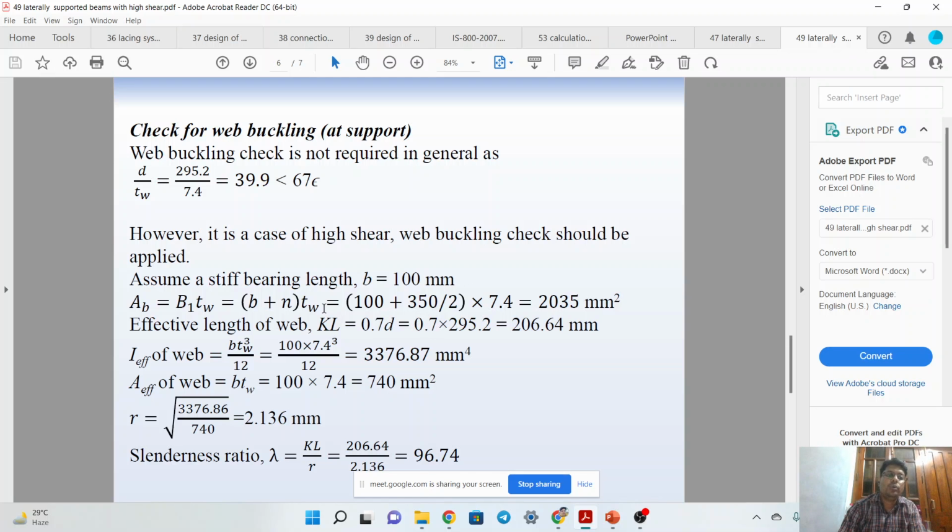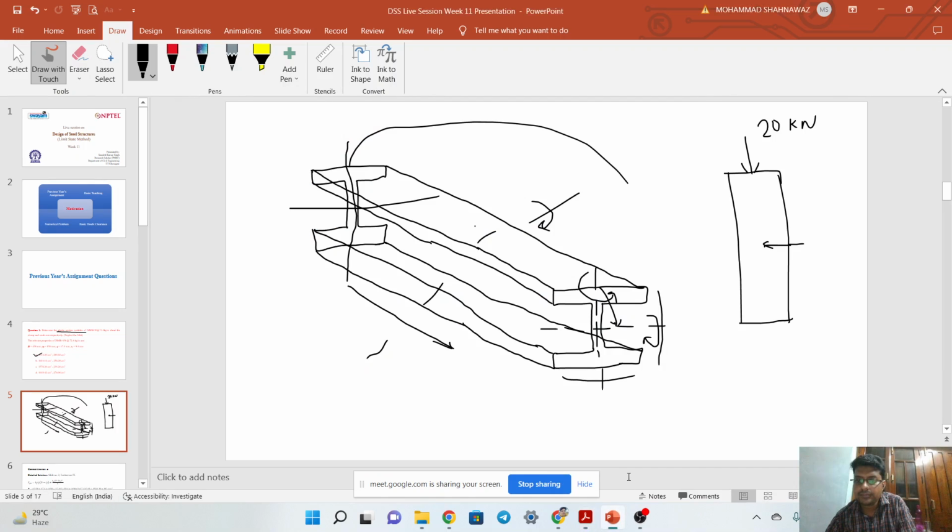So these are lateral dimensions. Remember one thing: whenever you get confused, you can always assume in layman's terms like this. Let us suppose you are provided with a rectangular column, and you see that after applying some load, it is buckling. It deflects. So this is your column, and this is the length of your column. I'm not talking about lateral length, this is the longitudinal length of the column. So what will happen when load comes? You see that it is buckling like this.